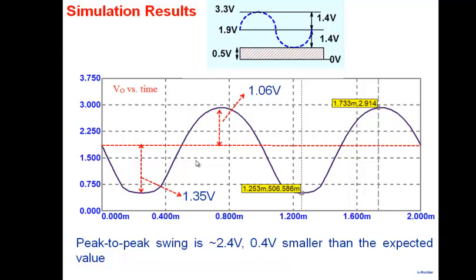If somebody asks you for a number, we want a number of how much is the peak to peak output voltage swing. What would you say? 2.4, 2.2, 2, what? What value will you say? Maximum voltage in at which the total harmonic distortion is less. So the point is the specification of peak to peak output voltage swing is incomplete until you specify what level of distortion. So you say I'm getting a 2 volt peak to peak swing at a harmonic distortion of so much. Then only your sentence is complete.